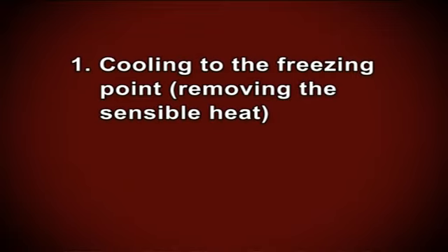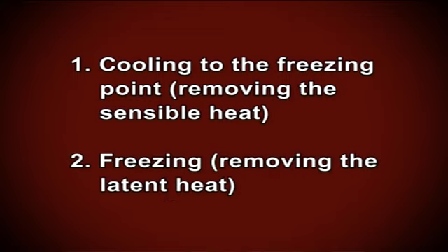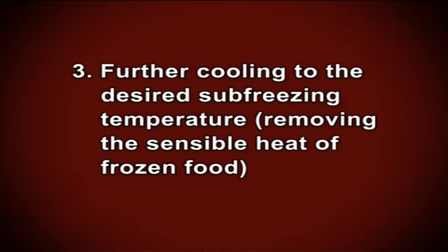The freezing of foods involves 3 stages. 1. Cooling to the freezing point, that is, removing the sensible heat. Number 2 is freezing, or removing the latent heat. 3. Further cooling to the desired sub-freezing temperature, that is, removing the sensible heat of the frozen food.